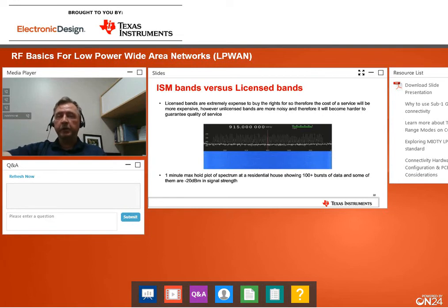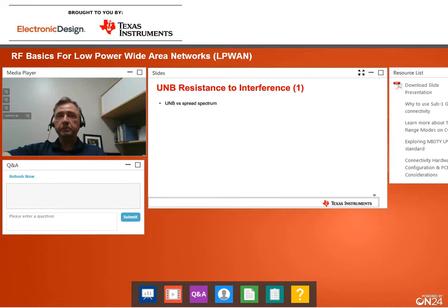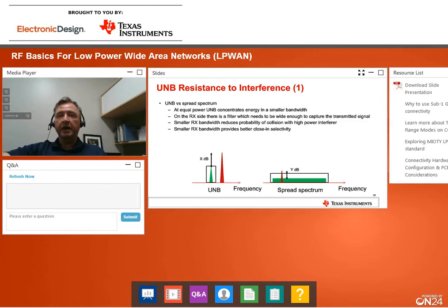So this is a very high signal strength that I'm getting at some suburban house somewhere in the middle of Dallas at 915 megahertz. So this means that these interferers are prevalent throughout all of our homes, suburbs, everywhere that you will see. So this needs to be accounted for in the products that you work with. And this is why we are a strong believer of narrowband over spread spectrum technologies, including LoRa. So for these narrowband technologies, they can withstand having a large blocker like the ones I just showed and we can still have a narrowband signal. This little box is signifying my narrowband filter.